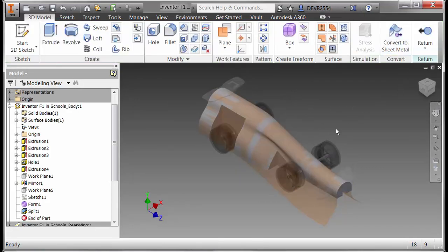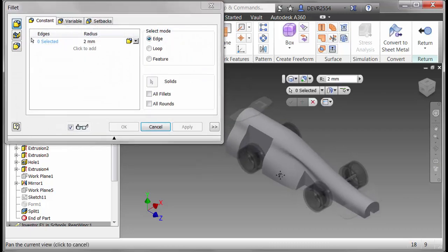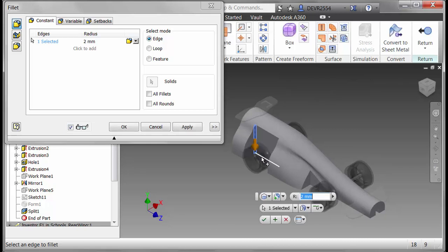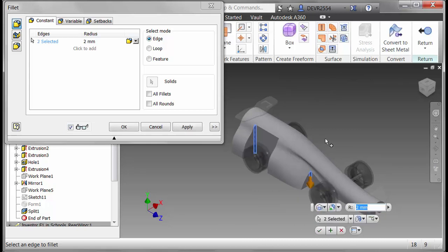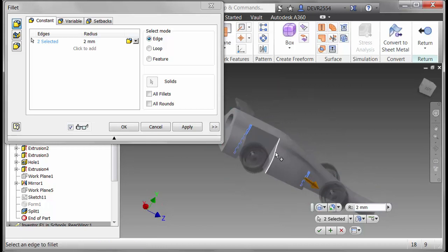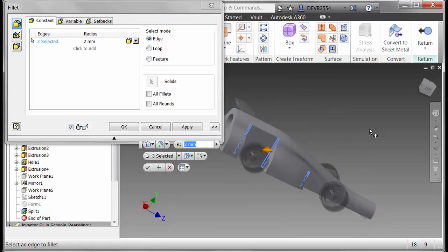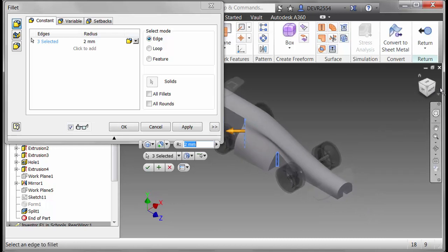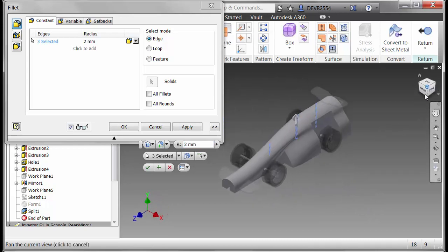Finish the freeform. And turn off the surface visibility so that plane is no longer visible. Now, I said that we need to think of both design and manufacturing. We can't manufacture those sharp corners on a CNC machine. I've been told it's a 6 millimeter cutting tool, so I want a radius of 3 millimeters in those corners. So I'm selecting 6 edges, 3 on one side and 3 on the other.